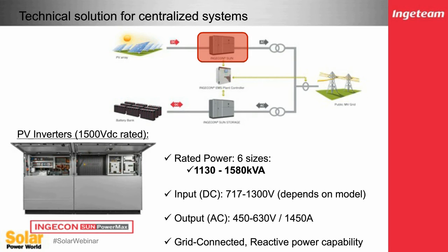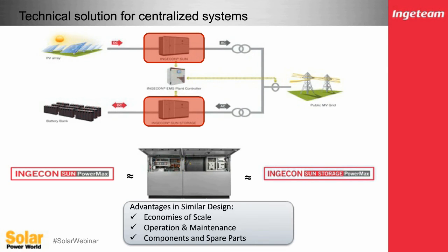So while you are taking advantage of standardized PV inverters and standardized battery inverters, an additional advantage is that this family of PV inverters and storage inverters are similar in their internal workings, and therefore you gain the advantage of one product family for PV or storage. This allows an ease of maintenance for operations and maintenance, and a lot of the spare parts can be similar to each other.